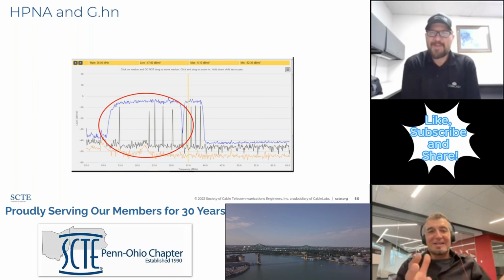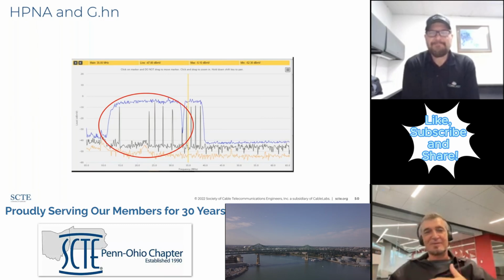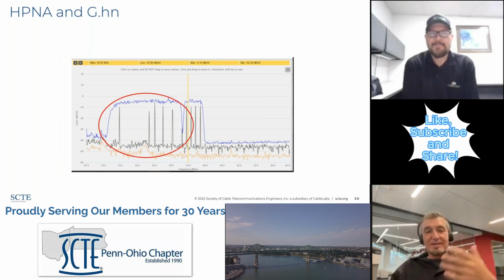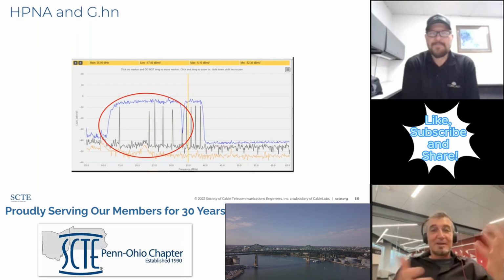Yeah, so now all of a sudden, hey, look how convenient this is, and all this extra spectrum we can use, and you're starting to see it above 100 megahertz, which affects our mid-split, high-split, full duplex, and all these other things. And typically, because of our forward coupling, that would affect the downstream of that house, and they're not a customer, so they don't feel it. But when we go into a mid-split and full duplex in these high-split environments, it starts to become an upstream problem where the entire node now gets wiped out because one customer switched to a competitive product and left connected to our plant.